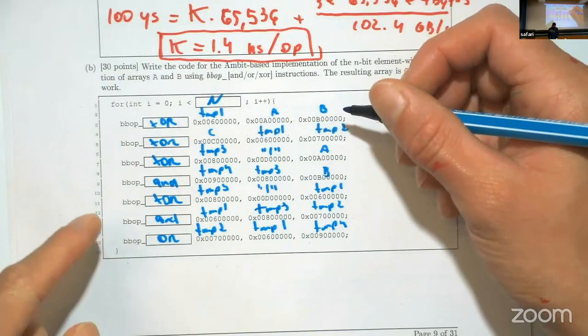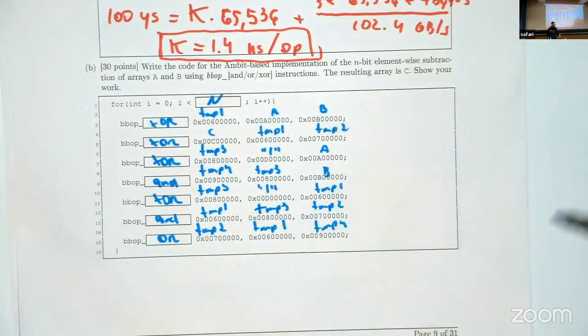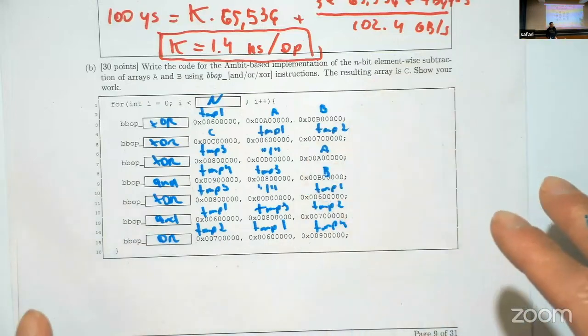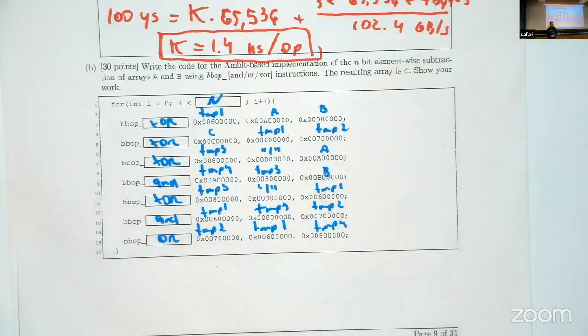It's because this is repeating n times. The way this is implemented in hardware later on is that there is an internal counter that is counting for this i and figuring out the offsets. The question does not ask you to figure that out, but if you go back to the SIMDRAM paper that I presented some time ago, I explained that there is a control unit that translates these bbop instructions into proper activations. Over there the i is a parameter, but it's transparent from the user, so you don't need to worry about it.